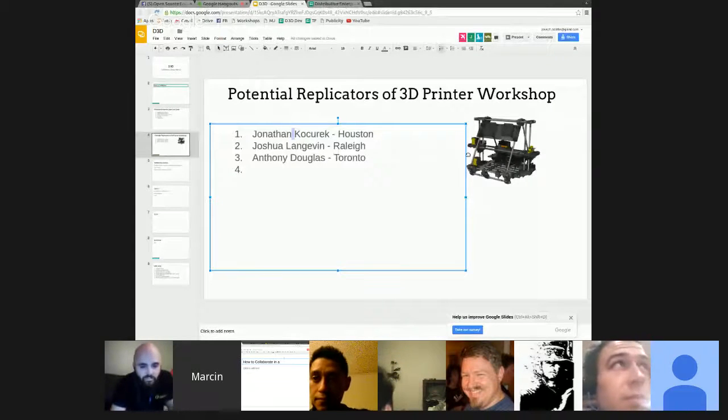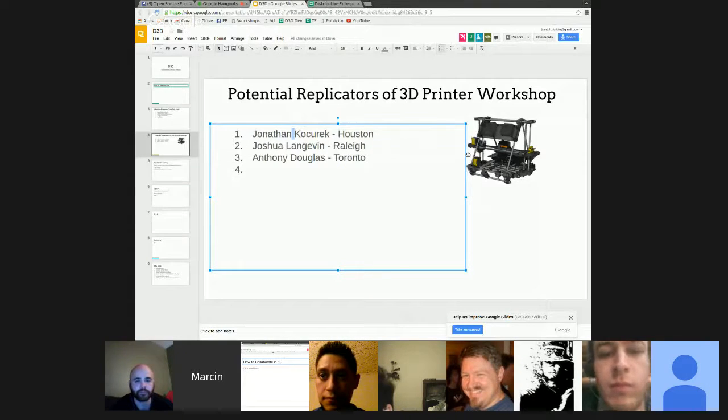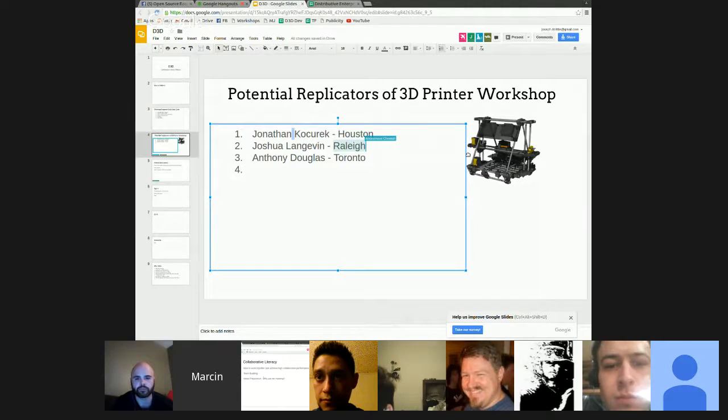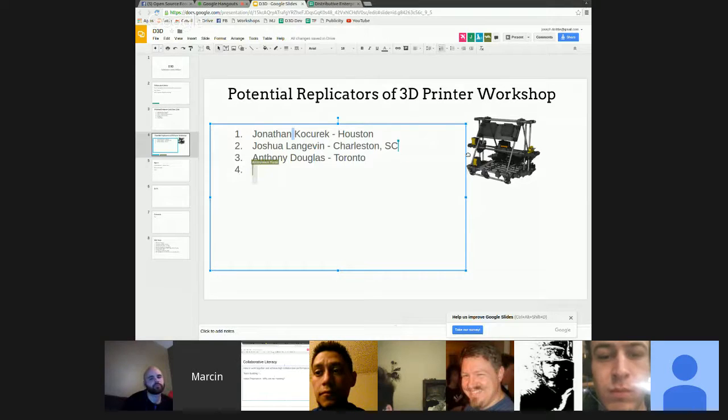We're already adding the bed leveling, so that's good. But we'd like to have an enclosure, because if you're printing large things, you're going to need even heat. It can't just start warping on you. We're talking about things like polycarbonate greenhouse panels, so we need the print quality to be really high. Polycarbonate is a thermoplastic, so it can be printed. And then you're talking about crazy productivity if you can do that.